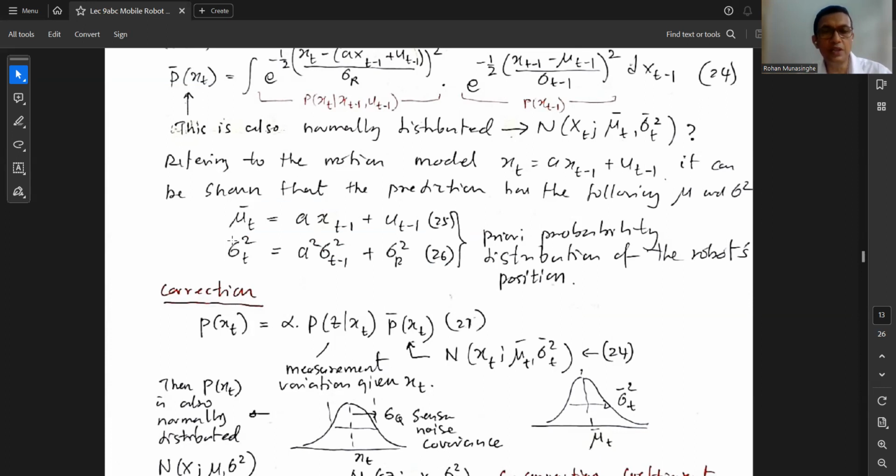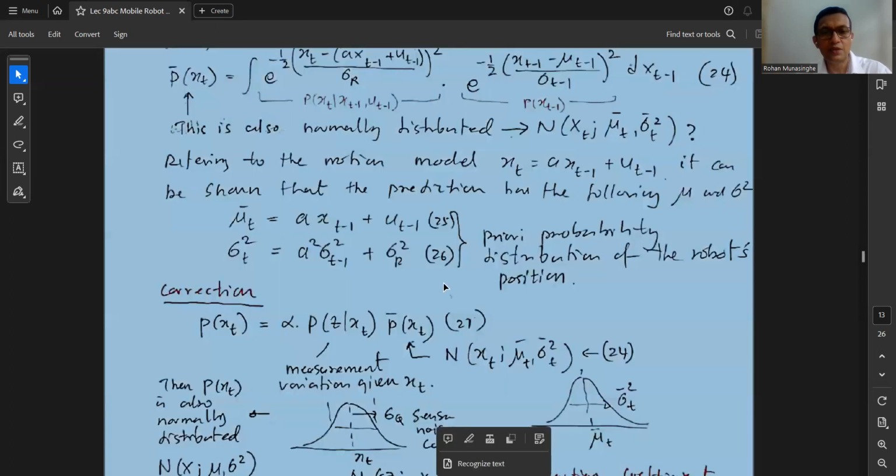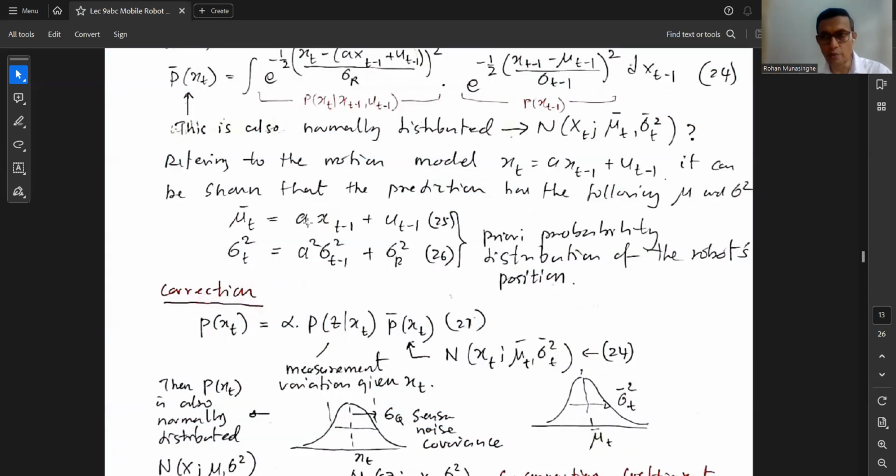Right? You can see very clearly, control signal comes in, it changes your state, your mean, and the transition equation is here, A, because even if you don't have any control signals, the dynamic model changes its position, right? The vehicle as it goes, even if you do not have any control signal or any gas, it will still go, right? Because it is self-propelling to some extent because of the stored energy. So that is basically A, autonomous state transition.